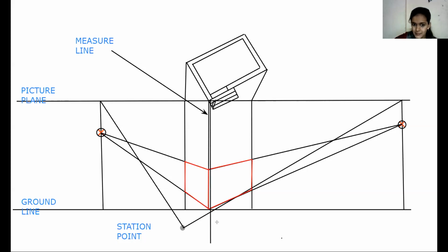So from the very first point, we have already drawn the major line, and draw the vertical lines from the next 3 points, and make sure that this time your vertical projections go below the ground line, because steps are going here. Our perspective view will go a little bit below our ground line. That's why. Now it's very easy for the other 4 points, this side of 4 points. We know how to connect them with the station point and how to drag a vertical projection from that.